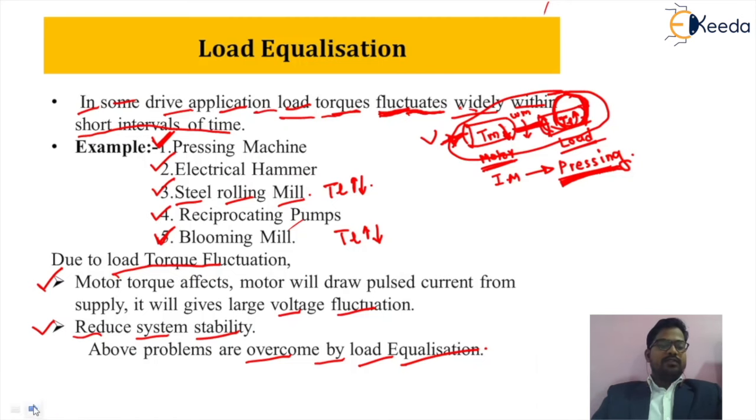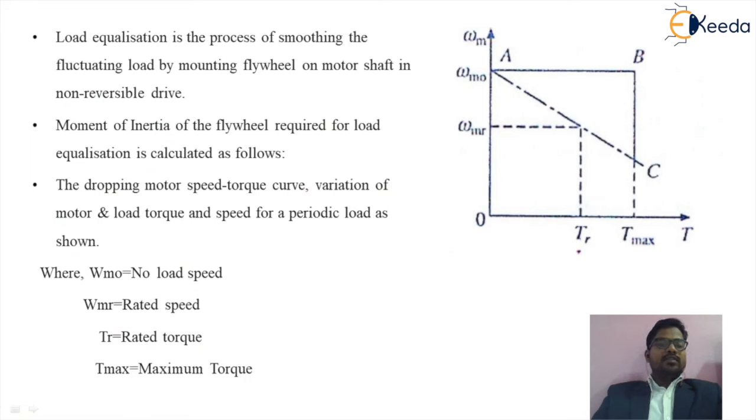So friends, load equalization is the process of smoothing the fluctuating load by mounting a flywheel on the motor shaft. This is a very important concept: we use a flywheel on the motor shaft, and due to that flywheel, the fluctuation of load torque is reduced.